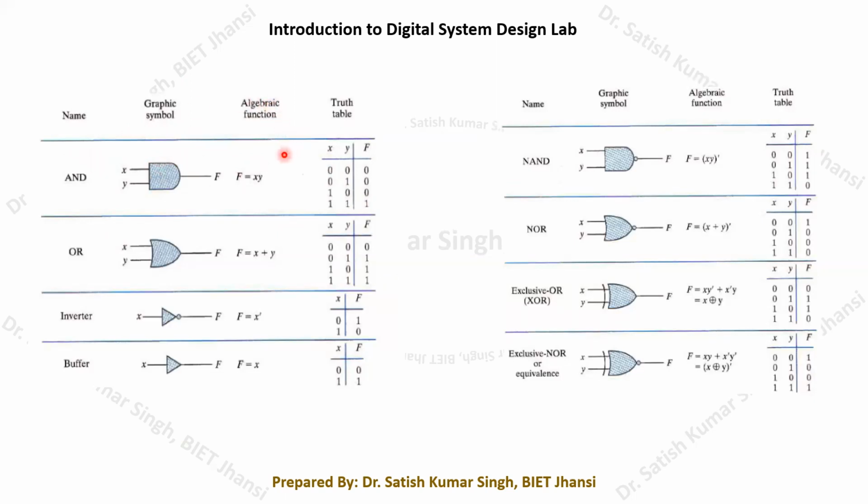That closed switch will be regarded as logic 1. Whenever the switch is opened, it will be regarded as logic 0. Therefore, even if one switch is in the open condition, the signal cannot reach the output, and therefore our output F becomes 0.